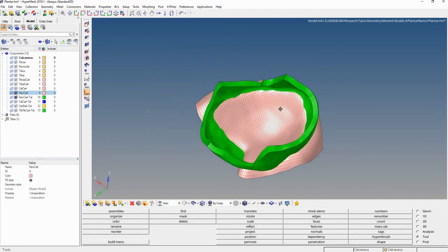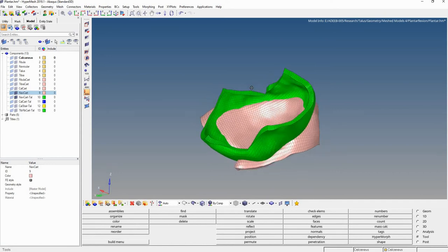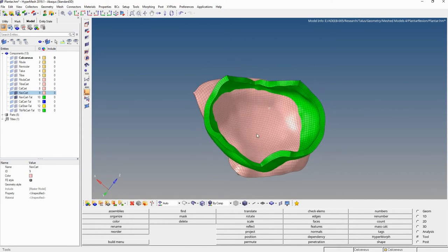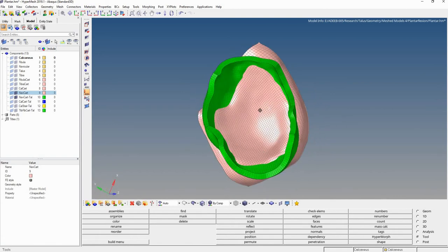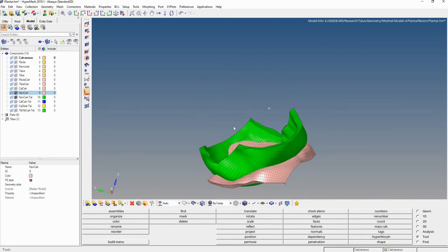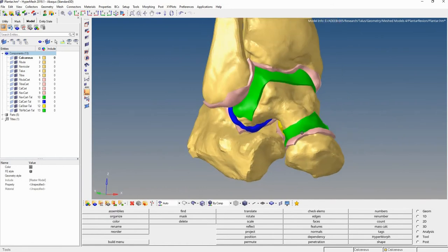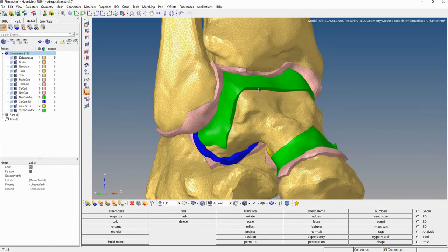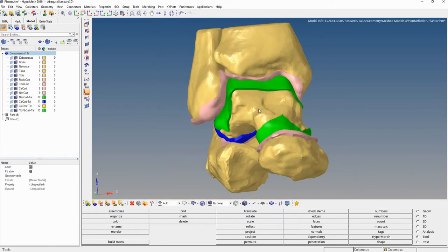If we use their current positions, it will definitely lead to errors when we run it in Abaqus. So the first thing we need to do is to leave enough gap between any contact.